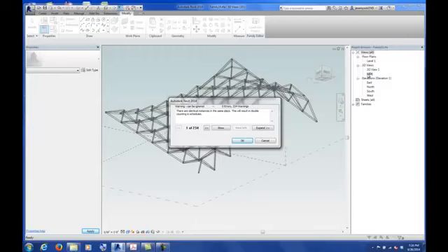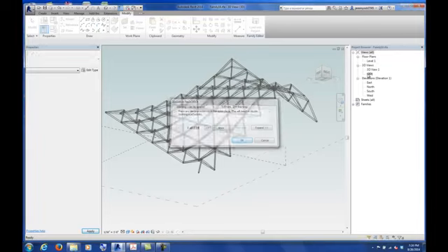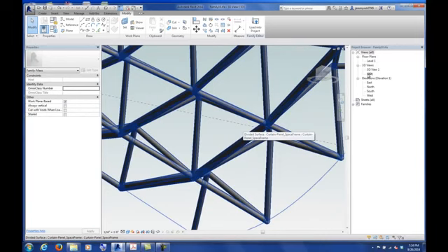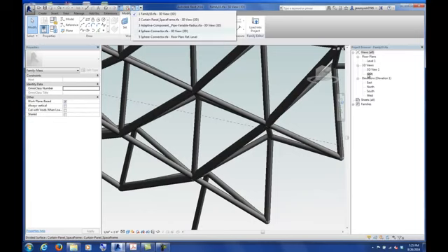I get this error message when I loaded everything into my space frame. It says there are identical instances in the same place. All that error message is saying is that I have spheres on every single corner. This is just like the pipe, remember? I have spheres on every single corner, and because of that they're going to overlap from repeated component. So remember last class, we made a yes-no parameter to turn on and off pipes. It's not really an error message, it's just a warning.